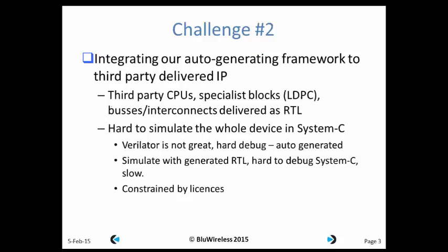The second challenge that we have is a lot of our framework is automatically generated. The IP blocks that we develop are parameterized in the SystemC, and that gives us a great deal of flexibility in putting systems together and also running what-if scenarios. What if we have an extra 8 bits on this bus, or what if we have an extra set of registers here, or a number of different ports? So we can play very flexibly with the IP blocks that we have.